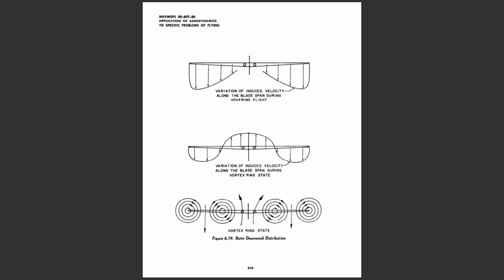By reference to the basic momentum theory, it is apparent that the rotor will produce no thrust in this condition if the net mass flow of air through the rotor is zero. It is important to note that the main lifting part of the rotor is not stalled. The rotor roughness and loss of control experienced during power settling results from the turbulent rotational flow on the blades, and the unsteady shifting of the flow in and out spanwise along the blade.